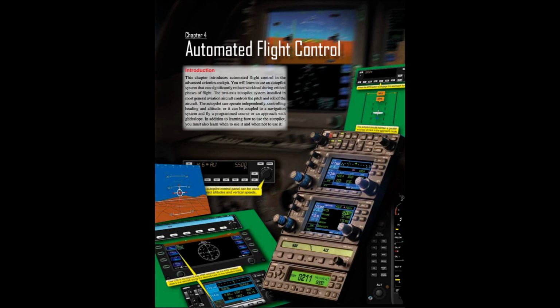You will learn how the autopilot and the flight management system, FMS/area navigation, RNAV, unit combine to create a fairly automated form of flight that places you in a managerial role. While the autopilot relieves you from manually manipulating the flight controls, you must maintain vigilance over the system to ensure that it performs the intended functions and the aircraft remains within acceptable parameters of altitudes, airspeeds, and airspace limits.